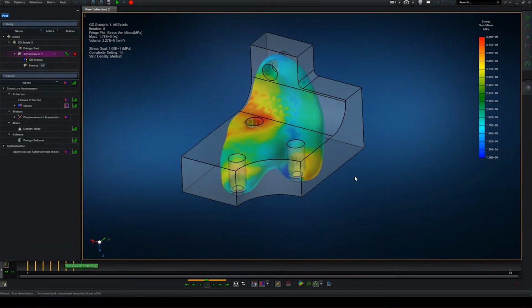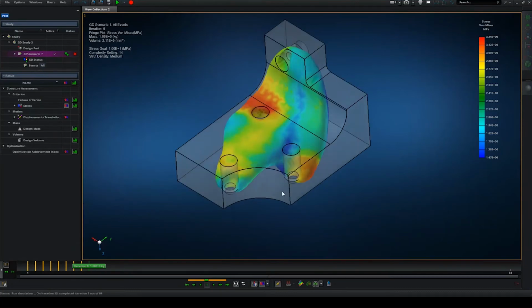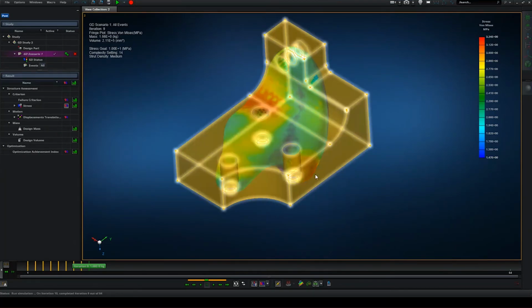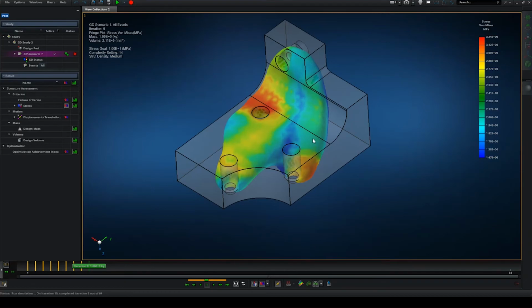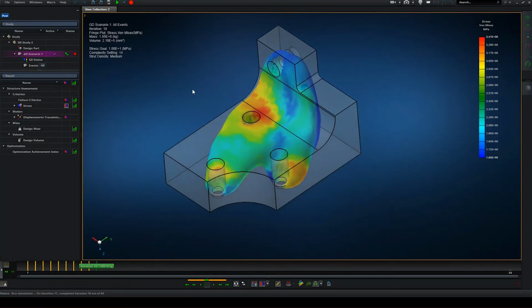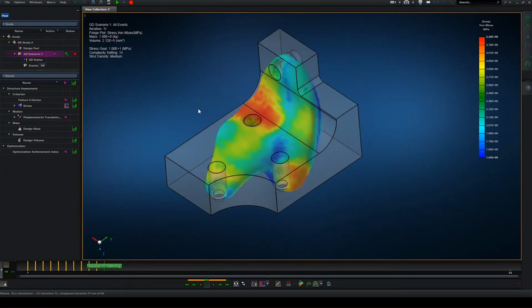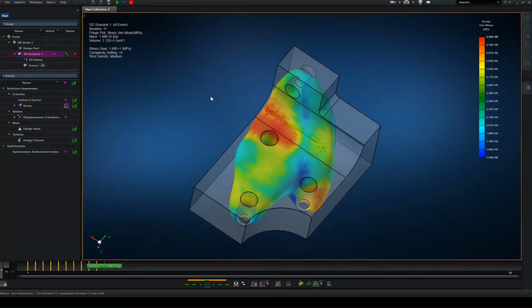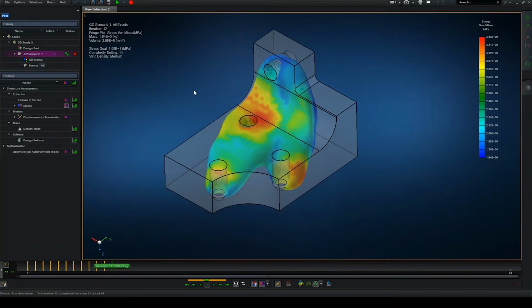Generative design doesn't lock itself into a branch of development. If it sees that it has now removed material, but the stresses are increasing beyond what is acceptable, it will actually come and add material back. It will just never add material beyond the initial domain that you specified. But there are nice examples where it removed material, the stresses developed higher, and it actually reverted back to earlier designs and brought that material back.